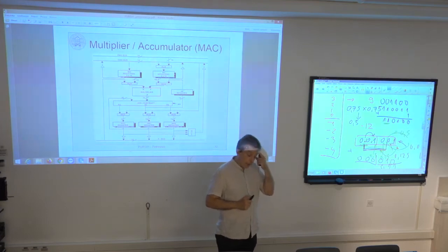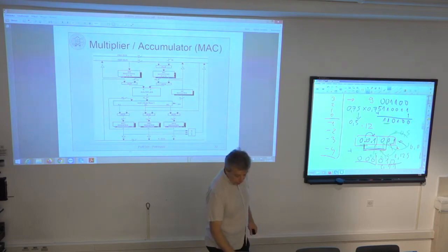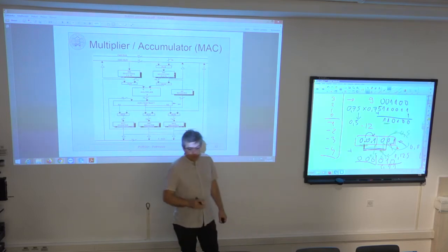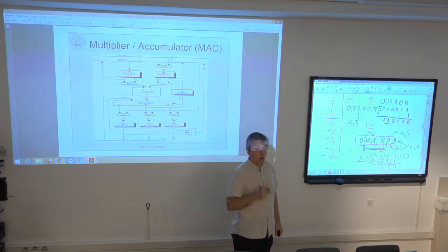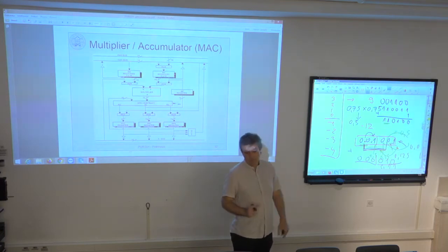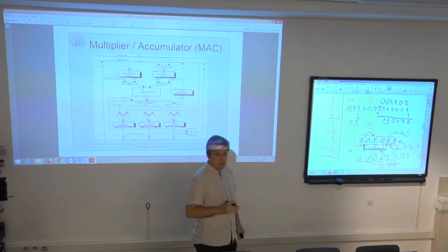And this kind of behavior can introduce bias. When you have this repeated rounding up of the midpoint value, it can create bias in the final result. And then they say, why don't you do some kind of unbiased rounding? So only in the case when this remainder is 1/2, toss a coin. And based on the result of this random experiment, either round up or not. Okay, so that is the idea, to have an unbiased rounding only for the case when the remainder is 1/2.